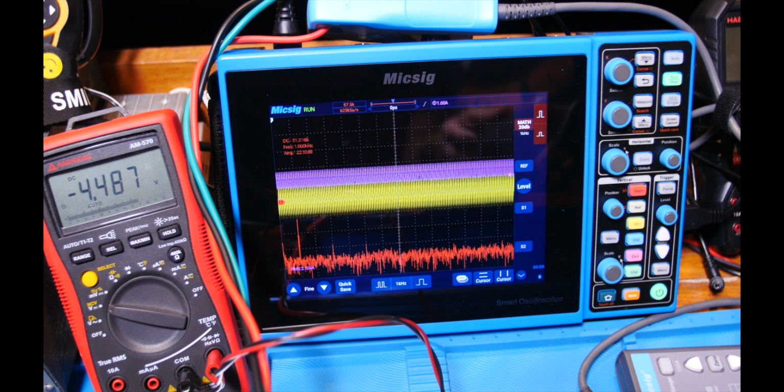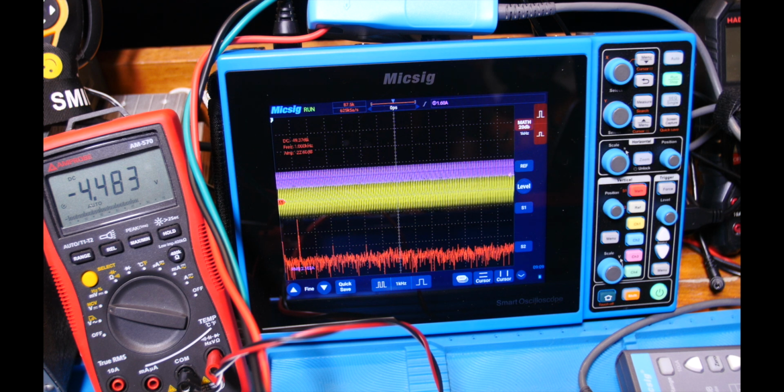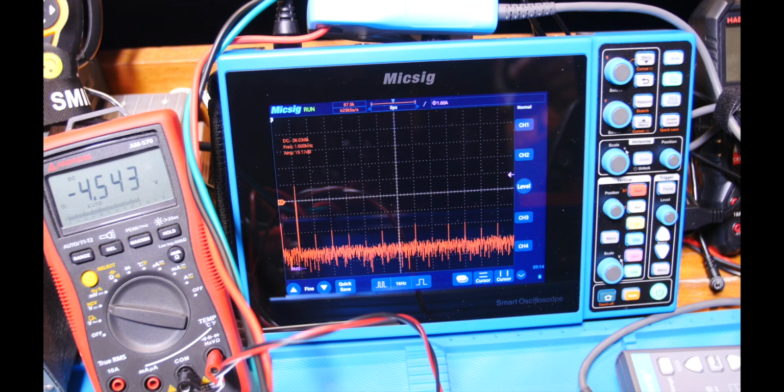So I think what we want to do is, when we get our power supply and everything else set up, we want to set this bias when we have our max signal in to give our max signal out that we want. And then you can see how low the distortion looks at this point. So I think that is the optimal setup we want once we get our power supply arranged and our max signal. And that's with this power supply set up right now with our lab bench.